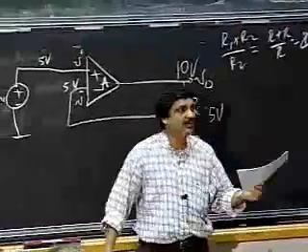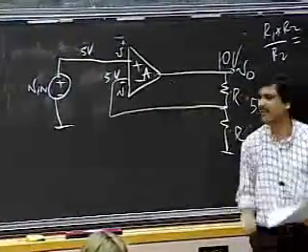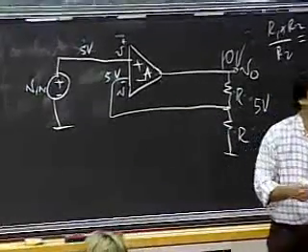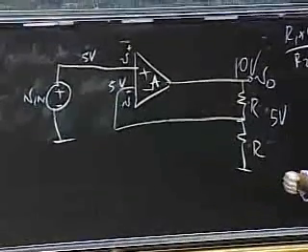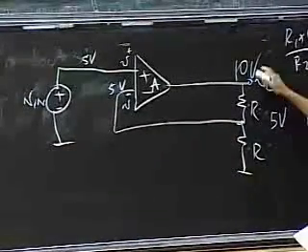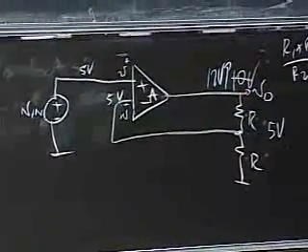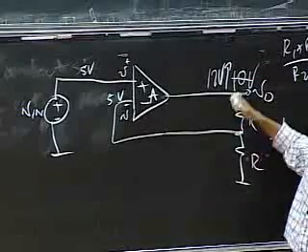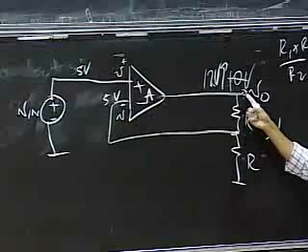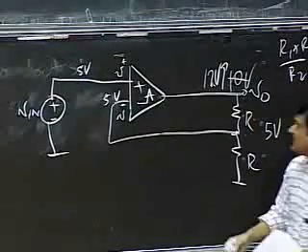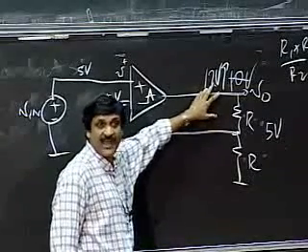So let's suppose that because I'm heating it, A suddenly tends to increase. It wants to increase because I've heated it. A is saying, I want to get out of this mold here, and it's trying to break through its shackles. So let's say, as a Gedanken experiment, that it tries to push it up higher, up to 12 volts. The up arrow says that the increase in A is trying to push up V0 momentarily. So let's say this goes to 12, hypothetically.